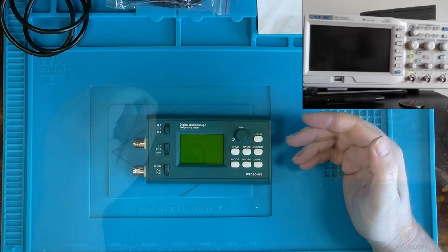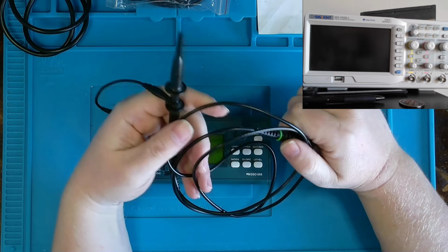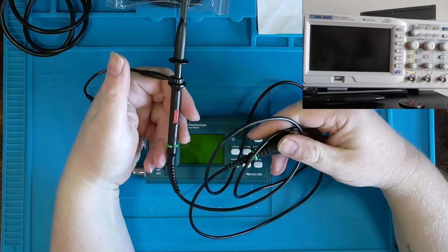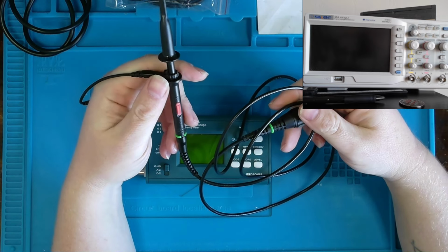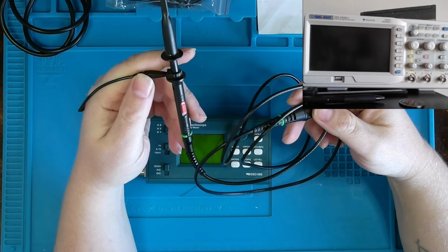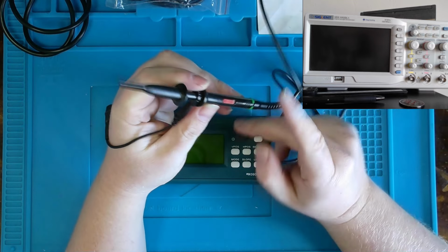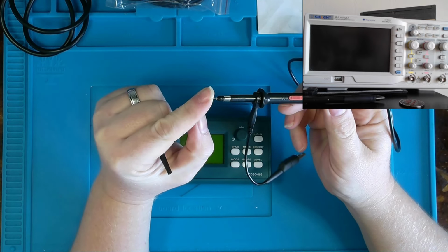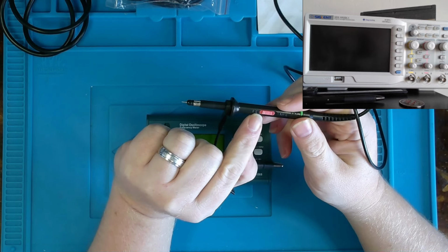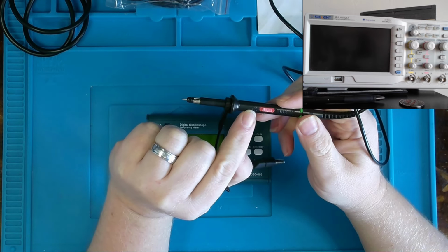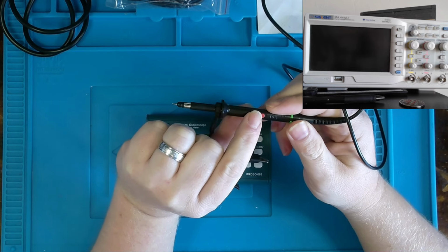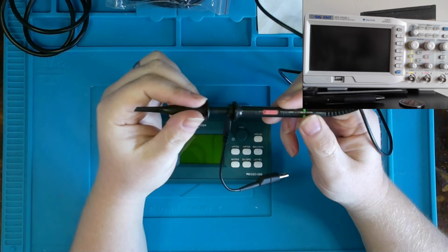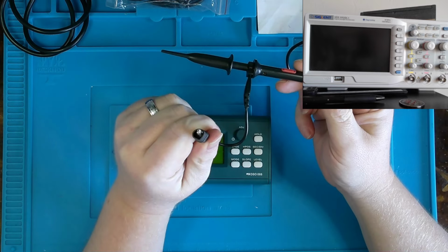Now, before we get into oscilloscope specifics, let's first talk about oscilloscope leads. This is your most common lead that you will use on an oscilloscope. This is what is often referred to as an oscilloscope probe or a probe. Now, common probes are going to have a nice fine point tip. A lot of times they'll have an amplification select switch, either 1x or 10x. So if you're needing to look at low-level audio, you could do so, as well as a ground clip,